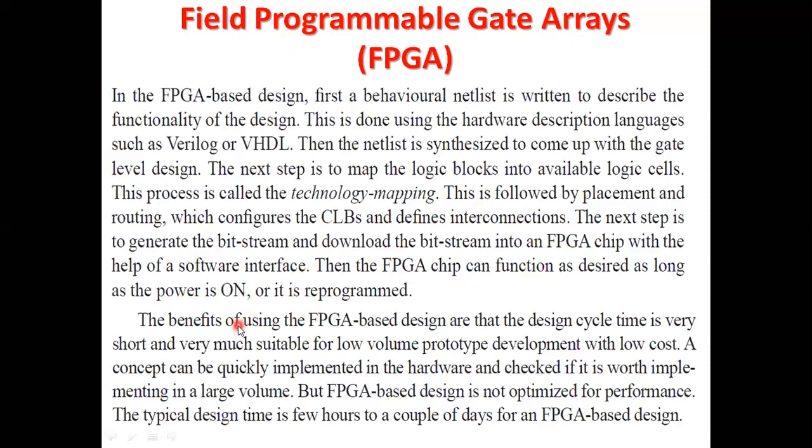The benefits of using FPGA based design are that the design cycle time is very short and it is very much suitable for low volume prototype development with low cost. A concept can be quickly implemented in the hardware and checked if it is worth implementing in large volume. But FPGA based design is not optimized for performance. The typical design time is a few hours to a couple of days for an FPGA based design. Okay, these are the disadvantages you can say, and these are the advantages. So you can see that FPGA has many advantages.